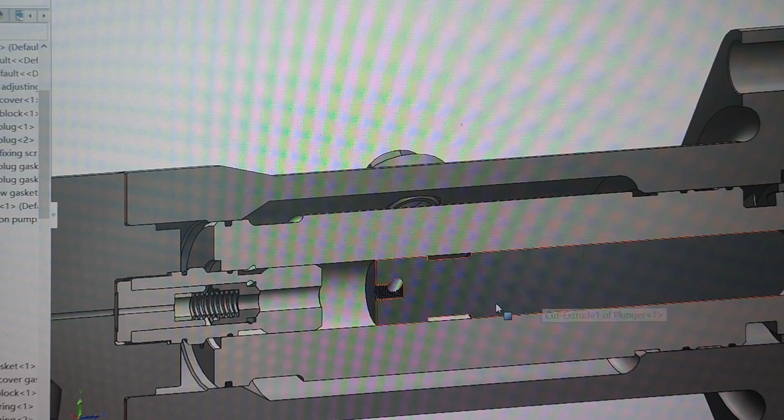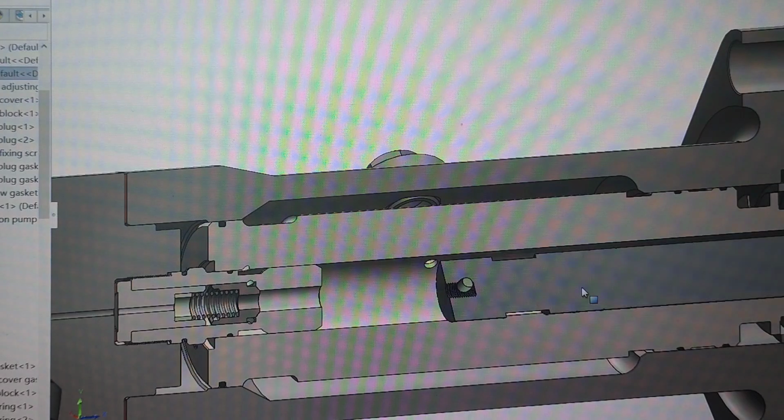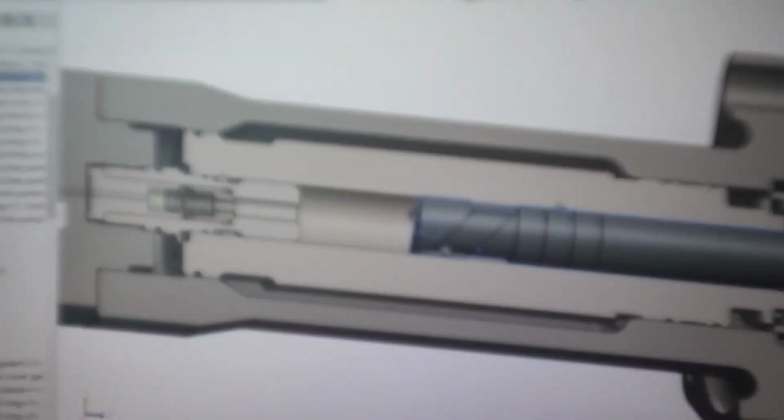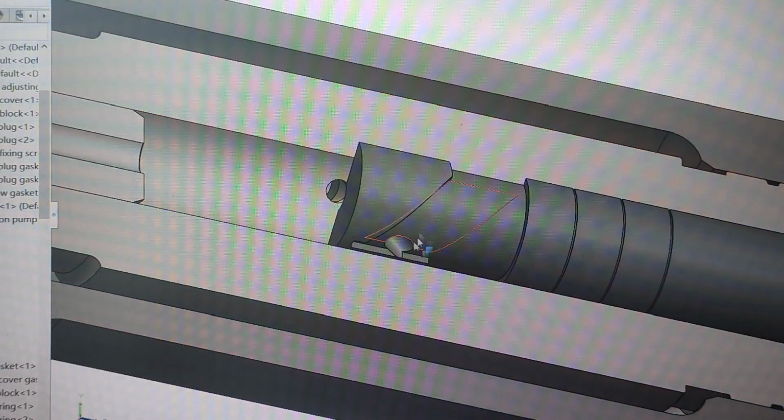So if you are very familiar with the fuel pumps, you may notice that the plunger assembly, like this, has something like this, the flow back port, right? So the end of the injection is actually adjusted by this barrel according to the fuel quantity, right?